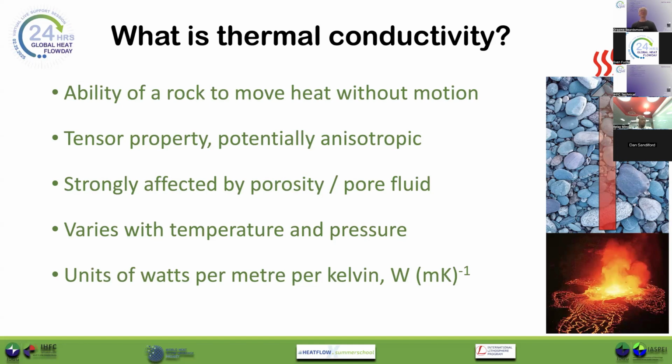So in practice, we typically only take a single thermal conductivity measurement, which characterizes the thermal conductivity either in a single direction through the rock, or the average, depending on what method we're using, characterizes the average thermal conductivity from heat expanding radially from a heat source.